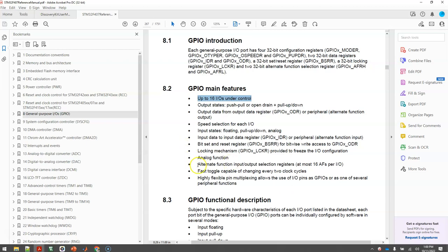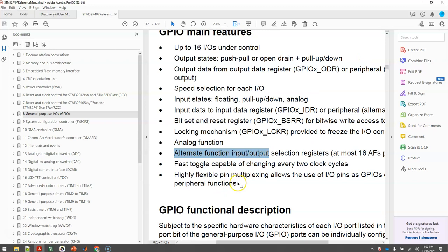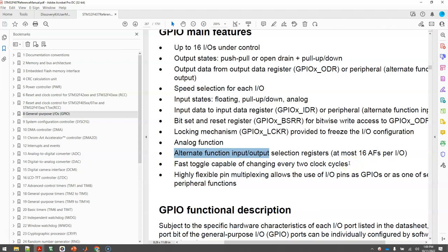There's yet one more thing called alternate function input output. So each of these GPIO pins can also be used for an alternate purpose, that is not just a simple input output. An alternate function can be a UART channel, an SPI serial protocol, I2S sound communication protocol. It could be USB on the go. It could be connection to your flash memory, all the data and address bits connected to your flash memory. So more than just using that as a GPIO, it is being used as a specific functionality.